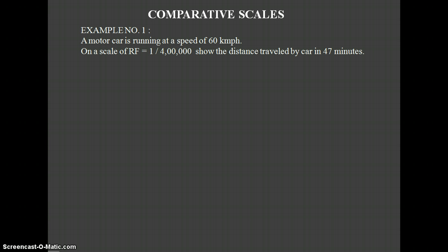First, assume 60 kilometers as the maximum length of the scale. For constructing a scale, we need to know the maximum length of the scale. Here, 60 kilometers per hour is given in the problem, so we take 60 kilometers as the maximum length of the scale.